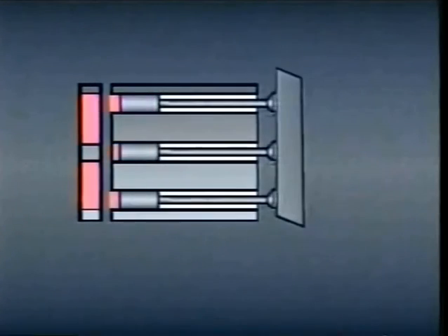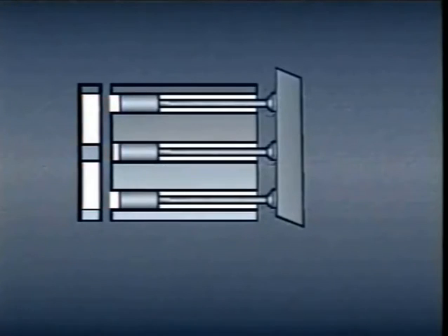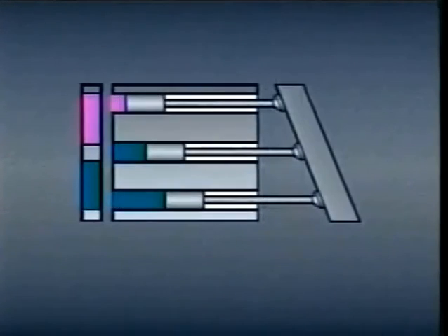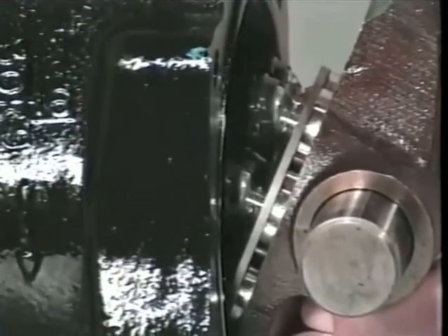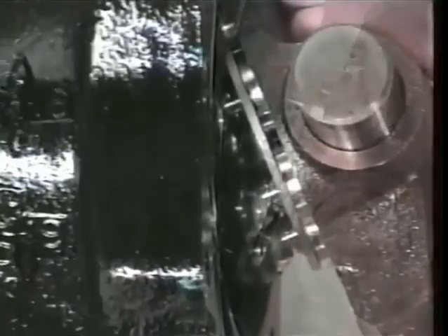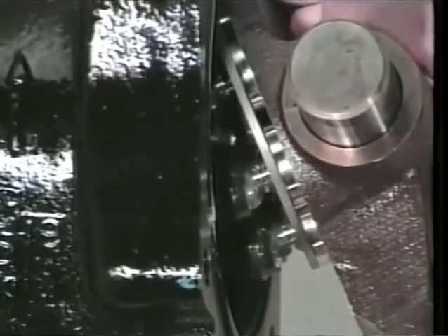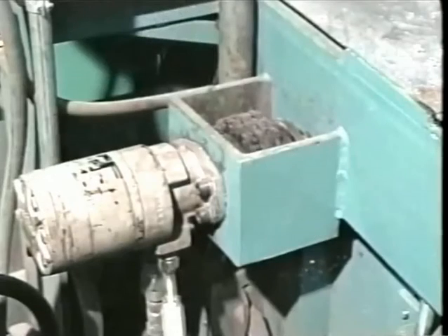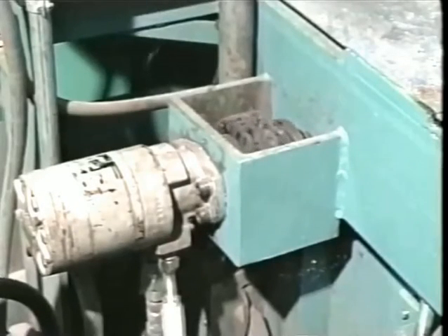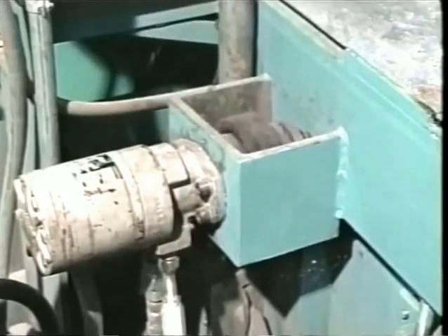Usually, to reverse direction, the motor is stopped. When the motor is restarted with the swash plate tilted over center, the piston shoes, which had been rotating in one direction, go back the other way, turning the cylinder barrel in the opposite direction and reversing the direction of the motor shaft. Both speed control and torque control of hydraulic motors is common in industry.